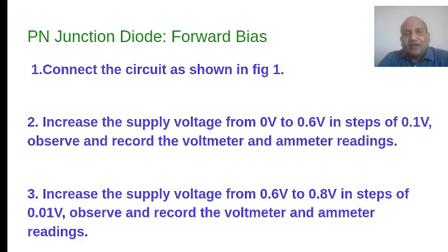This is why you can use your PN junction diode in forward bias as a voltage regulator, which can supply roughly 0.7 volt. That is the cut-in voltage of a silicon diode. Here we consider the silicon diode. For a germanium diode, the cut-in voltage is 0.3 volt.